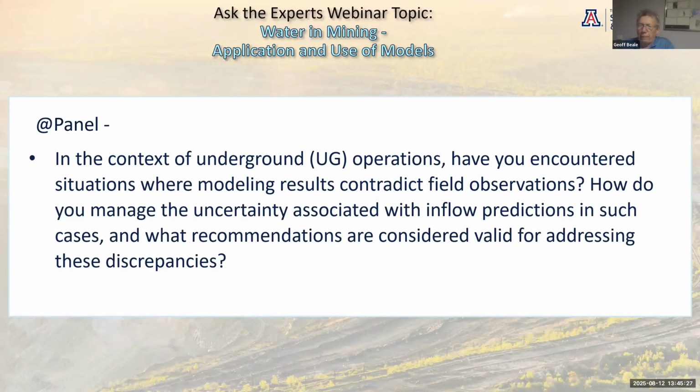Yeah, I've been involved with many flooded underground mines over the years, and more invariably, because you haven't drilled pilot holes or cover holes, sorry, ahead of the drift, or you haven't got dewatering holes into fractures. So if you're going into new ground on a heading or a drift with no cover, then, depending on the situation, you're potentially asking for unexpected inflows, which may give you a lot more inflow than you anticipated, and as Gus says, it's the peaks that you have to deal with.